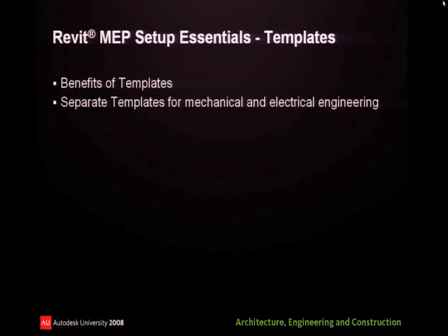We have separate templates for mechanical and electrical. That way, it seems like a nice move from traditional CAD to BIM. The traditional boundaries are respected, and with work sharing there's no mechanical person inadvertently doing something to the electrical design and vice versa. File size is going to be smaller. It just seems like the best workflow we have today.